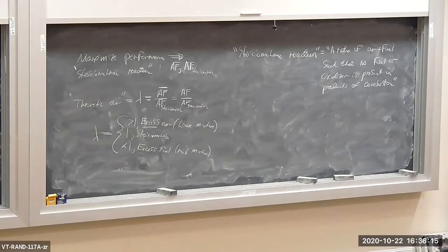And then when the early emission control stuff started coming in before catalytic converters, some manufacturers tried to go to a slightly lean mixture, providing too much air. The idea was to give the fuel as much air and then some as it needed to oxidize, and that would minimize emissions. Well, there are a lot of performance problems involving lean mixtures.